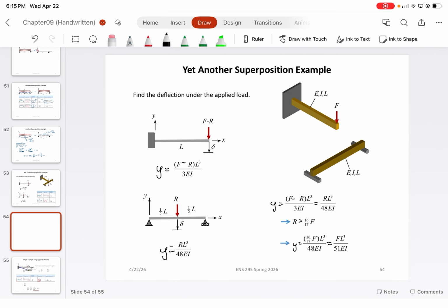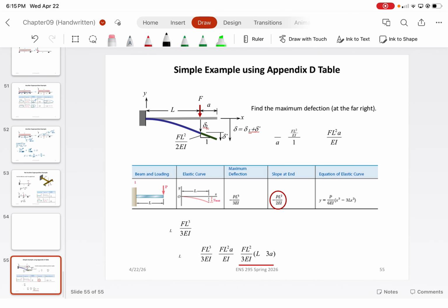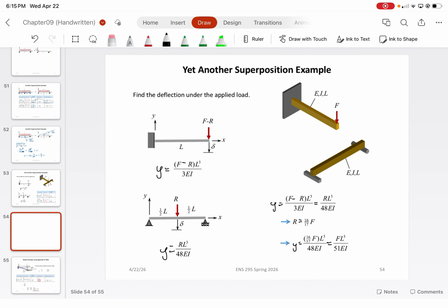Then, of course, you could solve for all of the other components accordingly. You could solve for the cantilever reaction forces, and you could solve for the simply supported reaction forces. It's basically the equivalent of solving for a cantilever beam with a spring beneath it. Make sense?